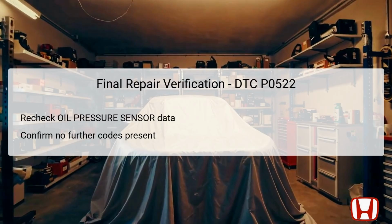After all necessary repairs have been performed, it is crucial to conduct a final verification of your work. Begin by rechecking the oil pressure sensor data using the HDS to confirm that it is operating within the expected parameters. You should look for a normal voltage reading, indicating proper sensor functionality. Additionally, ensure that no further diagnostic trouble codes, DTCs, are present in the system.